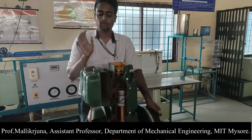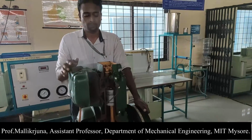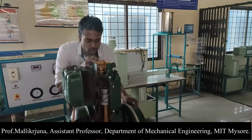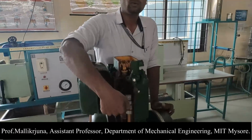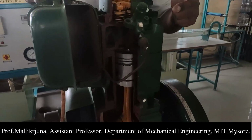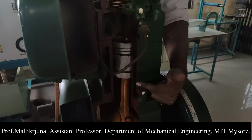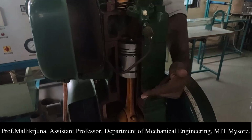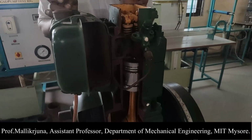Now I will continue the momentum to the flywheel because still the exhaust valve is open. So I am continuing the momentum. Exhaust valve stops its momentum now. Now if you clearly look, the piston has started the second cycle. That means the second cycle's first stroke is happening. What is that first stroke? Which is nothing but the suction stroke. Second cycle's suction stroke is happening. During that time, the exhaust valve is getting closed.